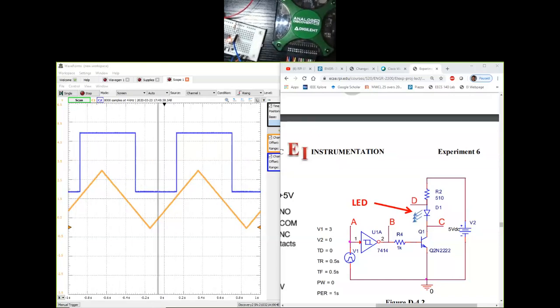Here is a good trick. If you have multiple 1 kilo ohm resistors, you can put two of them in parallel, make a 500 ohm resistor, and use that instead. So yes, you have the ability to do this experiment. However, it's not required. You just do it for your own learning. You don't have to do it. So just skip the building part, because in later experiments, it will become more of a challenge.